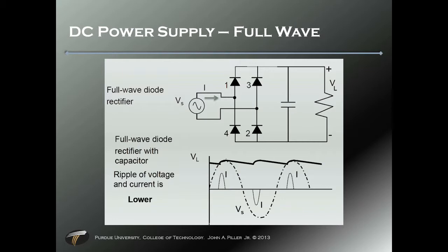It was able to do that because the way we have the diodes arranged, we're using not only the top half of the input wave signal, but we're also using the bottom half of the input wave signal. Hence the double the frequency, we have double the bumps on the output wave. Again, you still have the RC constant curve, but it's tighter and the ripple is tighter. The filter pulls in a little tighter to V peak.